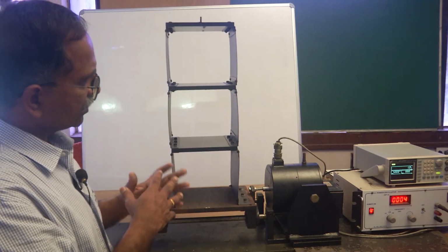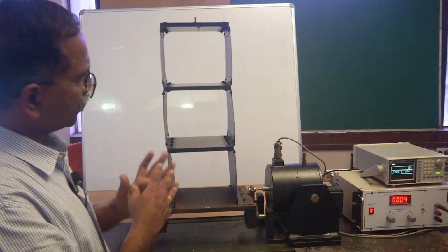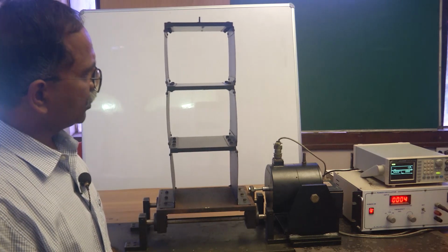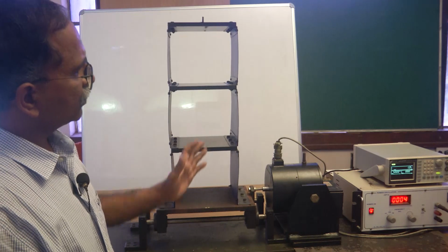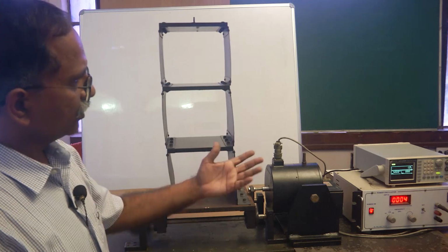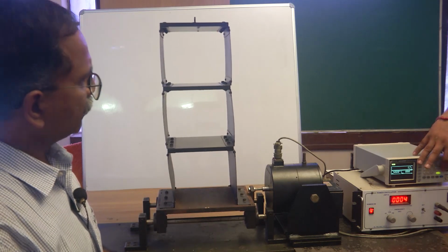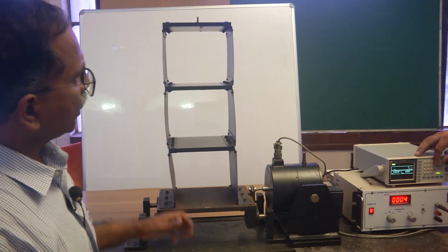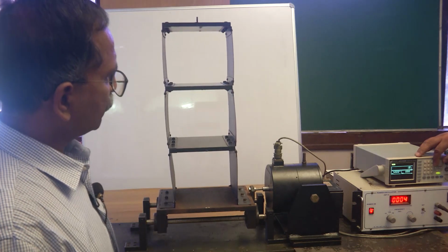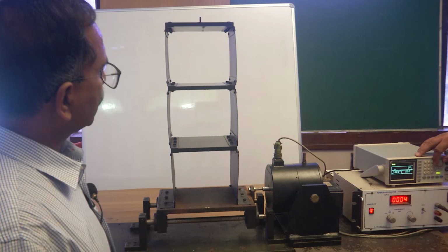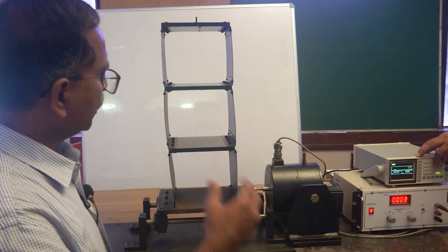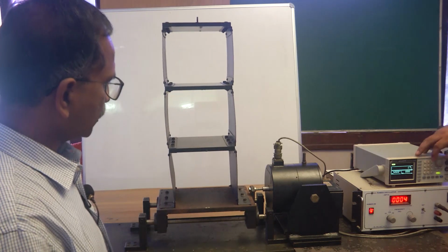When the system vibrates at its resonance, the mode shape corresponding to that natural frequency is exhibited. So, the operational deflection shape which we normally talk about is actually matching your mode shape corresponding to the given natural mode. Yes. So, now we will shift our frequency in steps and check for any other resonance that we observe. Now, obviously, this is a 3 degree of freedom system, and we expect 3 different resonances here, so let us see whether we get another resonance by increasing the frequency and scanning it past the second natural mode.